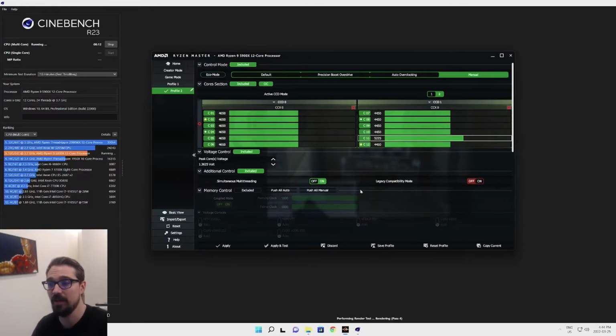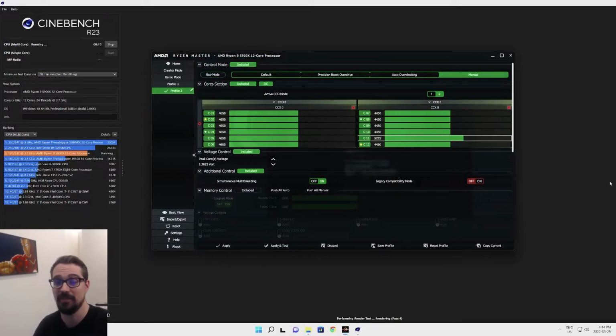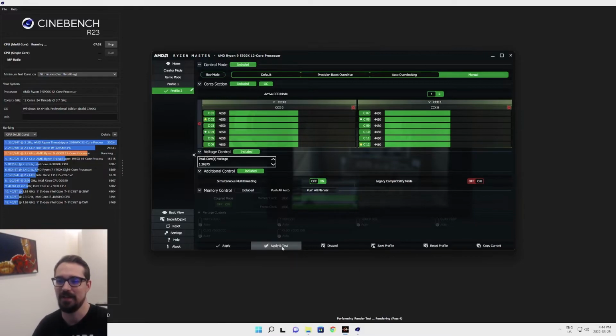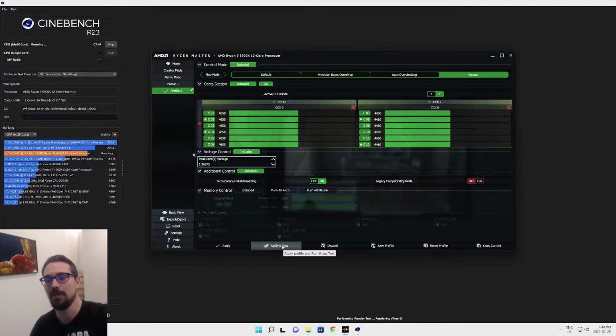So now we're going to apply this overclock. Oh, see there, I almost made a mistake. I put 5225. That would crash for sure, absolutely. So here, 4.6, that's probably good. We're probably going to need a little more voltage. I don't like going above 1.35 volts or 1.36 volts. I will, just for science, go as high as 1.4, but I won't tune anything for higher than about 1.36.